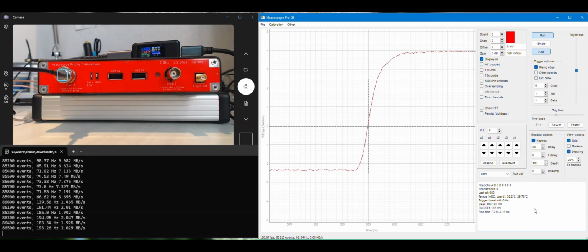Yeah, so doing good here. What else do we need to talk about? Basic ways to start and stop runs. So you've got your usual run and paused buttons here. You can also do single shot capture, so we're waiting for a trigger, and then when you press run, you just collect one more event. That's single capture mode, and it's waiting for a trigger.